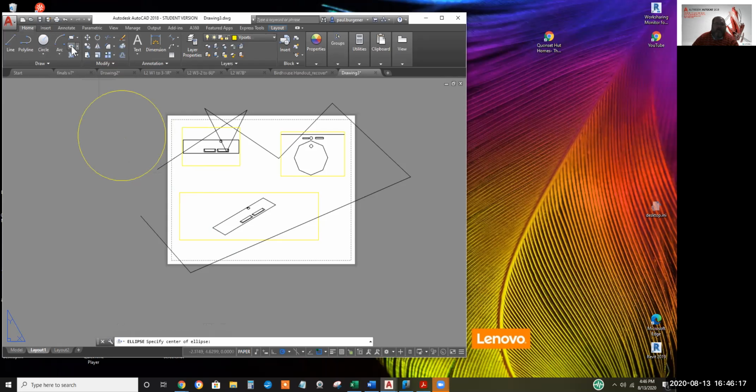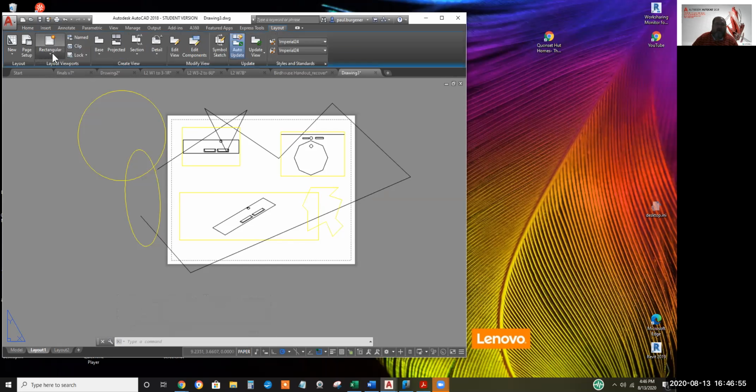I'm not sure. I'm shooting from the hip here, but I think an oval can be a viewport. We'll find out. By far, the most popular way is a polygon or a polyline. And when I do your handouts, I'm all the time making a viewport and wrapping it around C for close, so I get a close-up of the 3D view that I want without the parts next to it in model space. Anyway, I think you've got to modify them one at a time.